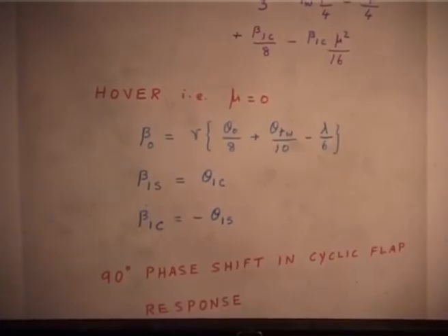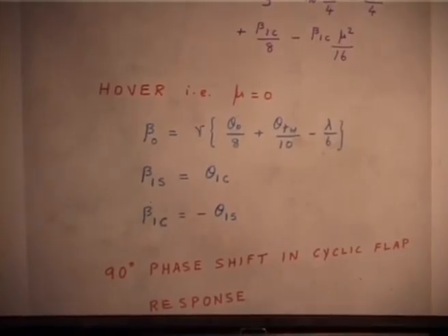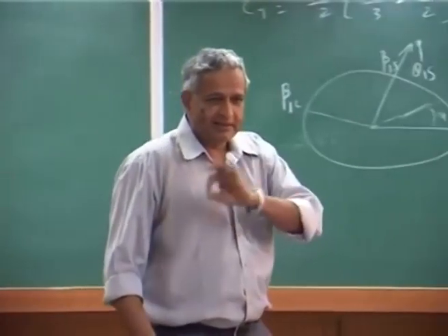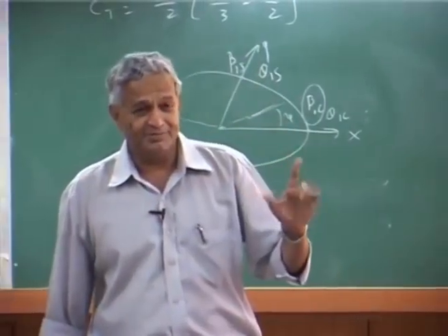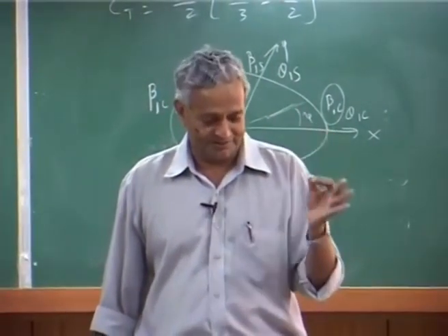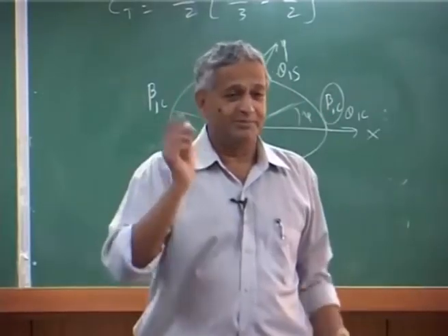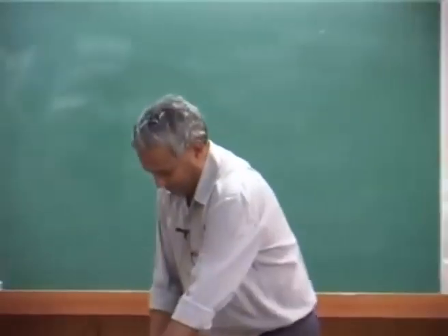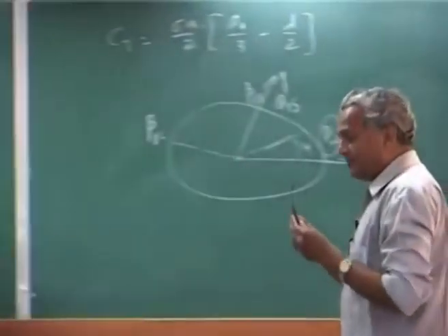Okay. It is a little interesting geometrical interpretation, I thought I will just show you. That is, all this for only centrally hinged, because when you say centrally hinged, immediately you must know flap frequency is 1 per rev. That means, flap natural frequency is just the rotor RPM itself, nothing else.